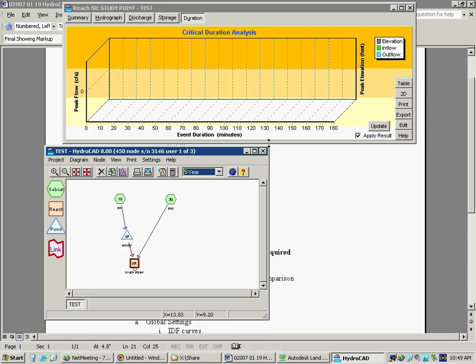Yeah. The way I see it is that it tries to leapfrog over the limitation of rational, that you can't have simultaneous storms occurring with different intensity values over the same site. And like I said, that's my view. There's other views on what it's employed for. We'll leave it up to you to decide. But anyway, I just wanted to show you how to use it and explain what HydroCAD actually looks at and how it determines what the critical duration is.